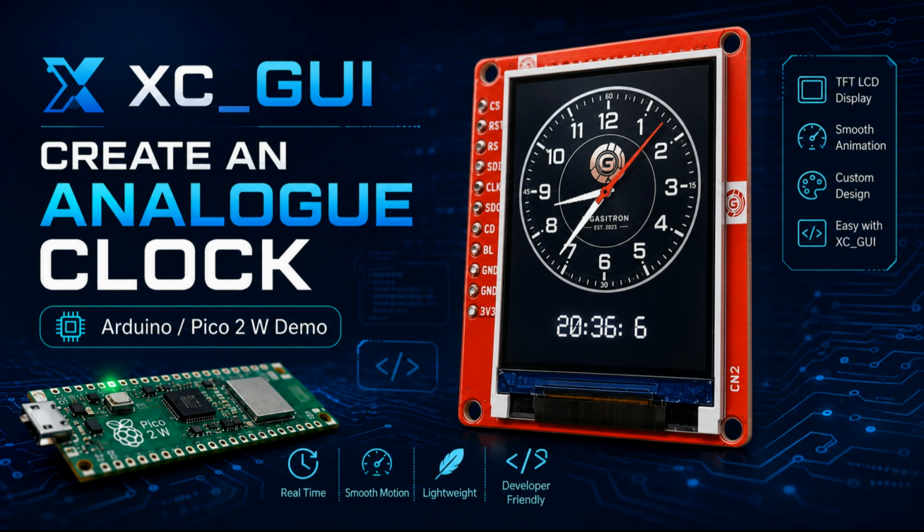For a complex touchscreen interface with multiple pages, buttons, menus, and animations, LVGL will normally be the better choice. However, for a smaller embedded application that only needs to display sensor readings, status information, simple graphics, or a custom interface such as this analog clock, XCGUI can be easier to understand and integrate.